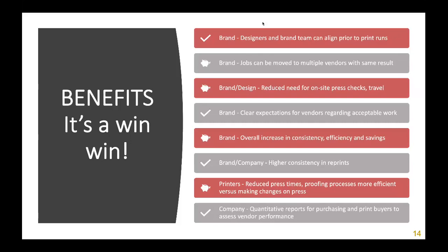For us, the paper is specified, yes, by us. And even if you're not in the United States or in North America, they do have different specifications for paper. Yes, we do. We use a pretty bright white sheet for our folding cartons, and we do specify the paper that we're using on the bags as well, which are printed gravure. So yes, we do hold them to a pretty high standard sheet for any of our folding cartons. That's usually the engineering team, and they're measuring that, asking for a certain brightness and whiteness to the sheet.